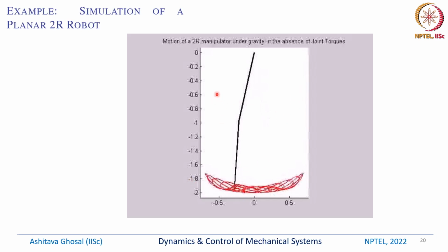I could have also plotted the motion of any other point on this link or any other point on this link. You know, MATLAB, once you find θ1 as a function of time, I can find out what the CG is doing. Okay, what is the CG? This is the distance R1 along the link. So we can plot what the CG is doing.